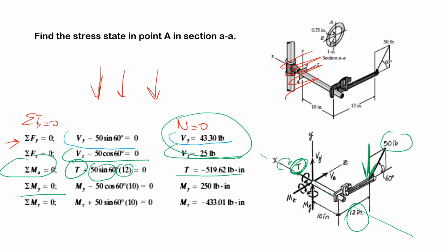And for bending, My. Y is this axis. So bending around this axis is caused by this component, and as you see, you have this moment arm times component. You see the signs we have taken are this. If you take this as positive, so like this, the other one is in the opposite direction. That's why I take the minus. So I find the My value and Mz.